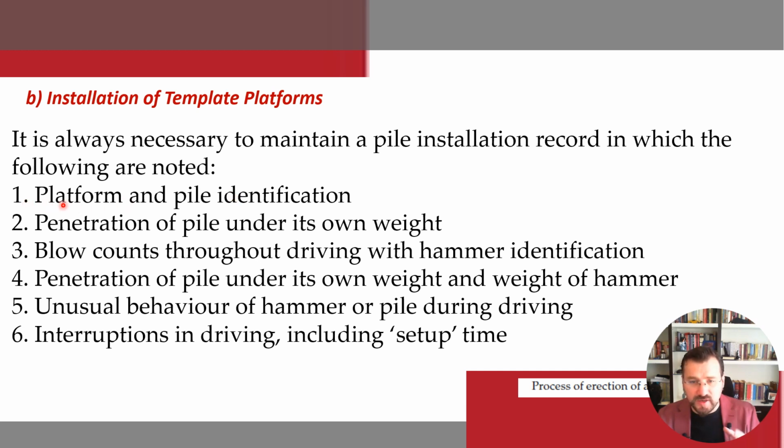First of all, the platform and the pile identification is crucial. Okay, so penetration of a pile under its own weight. Blow counts throughout driving with hammer identification. Penetration of pile under its own weight and the weight of hammer itself. Okay. So unusual behavior of hammer or pile during driving, interruptions in driving, including the setup time. So we have to care about this and some more I have actually. Let's go into details.